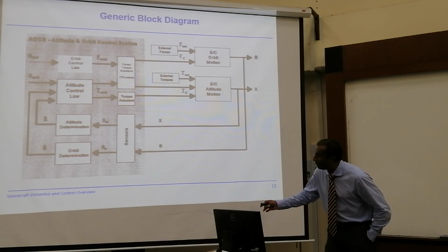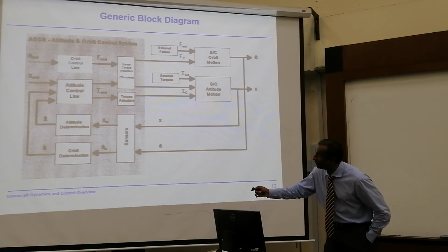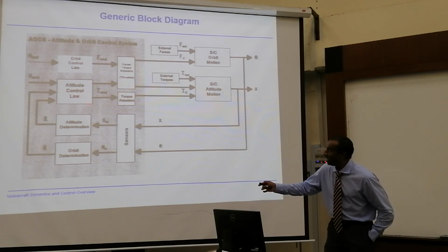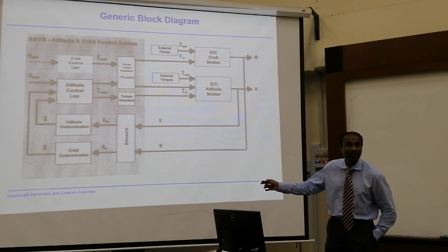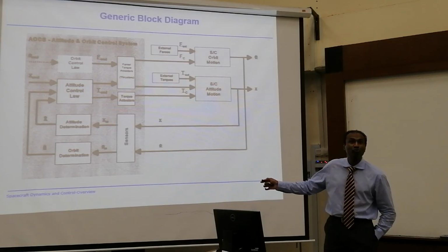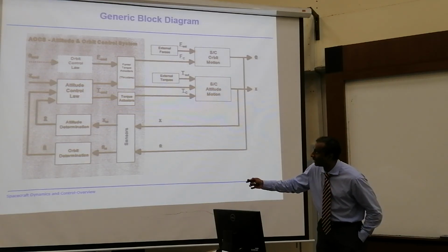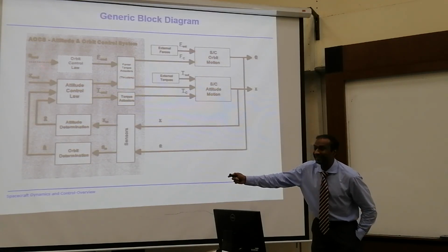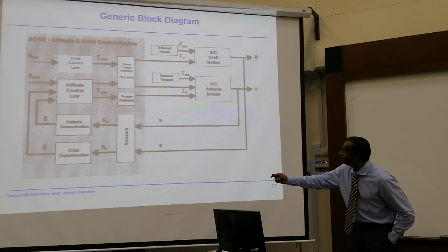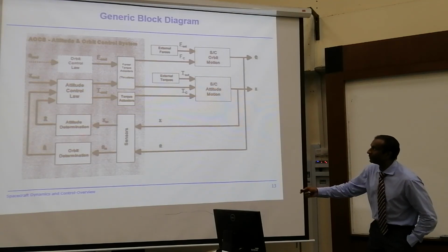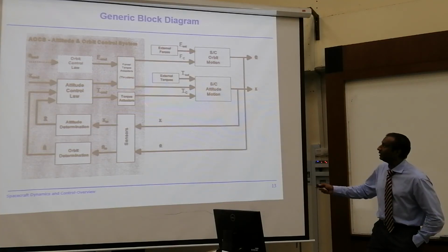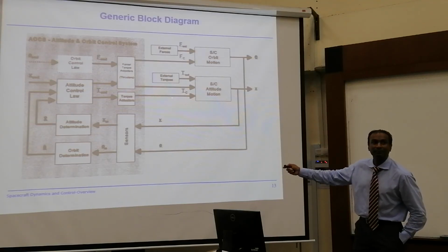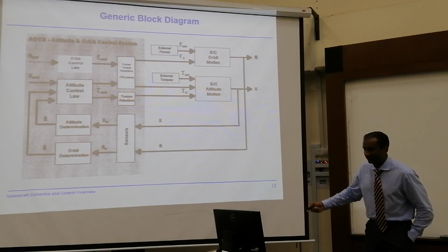Orbit determination goes here, comes back here, sensor. But this can be coupled because I have my control law also for my thrusters here. Thrusters can do orbit control. So you can calculate together and then feed back here how much you want to control the orbit. Remember, the daily job is here. This one, maybe 2 times or 3 times a year, if necessary. Okay?